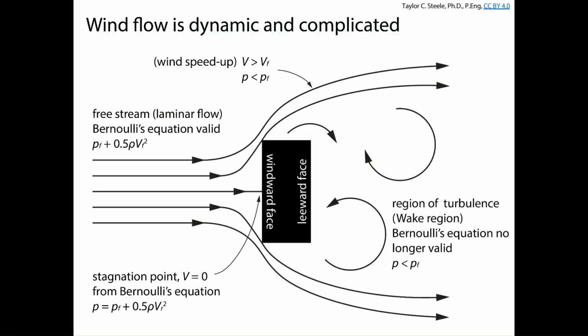The interesting thing about wind and even earthquake loads is that they're not really static forces. And unfortunately, we've been conditioning you in civil engineering courses to always consider the equations of static equilibrium. Sum of the forces is equal to 0, which means there's no net acceleration. Unfortunately, for wind and earthquake loads, there can be significant movements of our structures, significant accelerations, and that can cause things to be a little bit difficult.